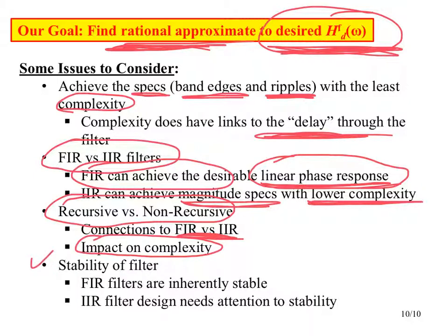And then finally, if we're designing a filter, when we're all done with the design and we go to implement this thing, we need to make sure that the thing that we implement will actually be a stable system. Otherwise, as soon as we start putting an input into it, the output will more than likely grow without bound, and that would not be good. So what we'll find is that FIR filters, by their very nature, are inherently stable. So that makes the design process easy.